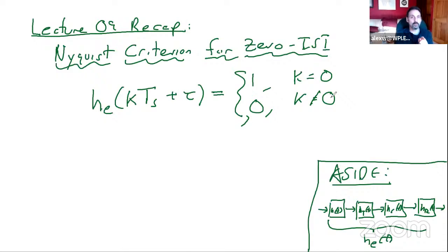There's one point: first of all, we're sampling the incoming analog continuous wave at the receiver. And the resulting impulse response, if we sample at the right point, because we adjust the difference between the clocks at the transmitter and the receiver, should give us the desired value we're seeking. And because we're sampling, every other sampling instant should be equal to 0.